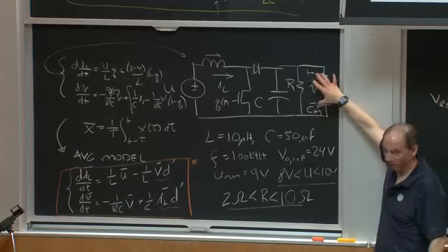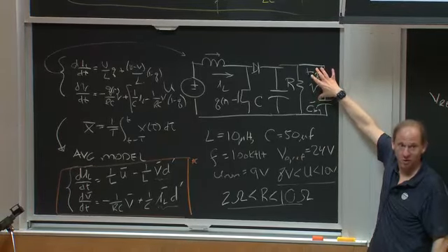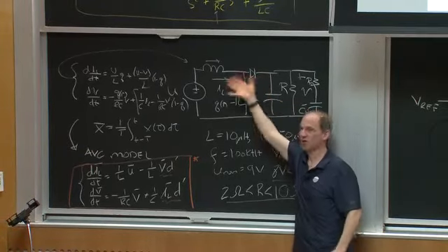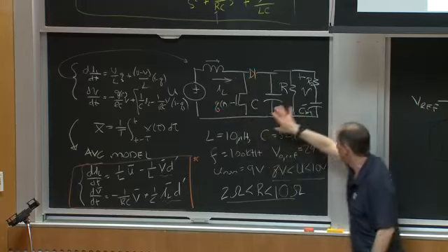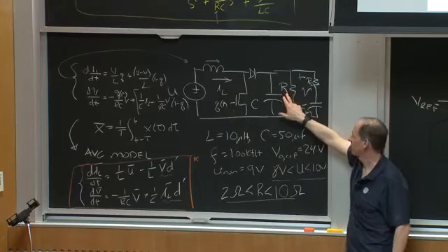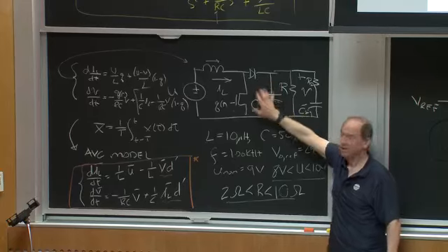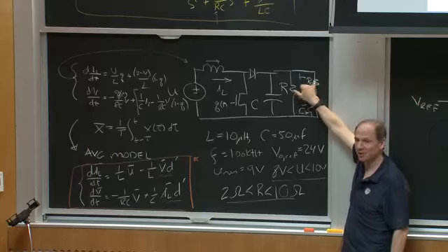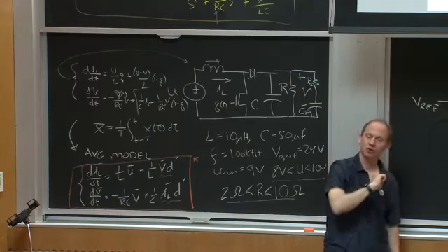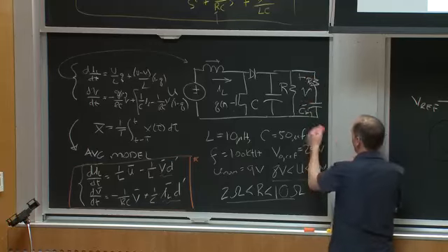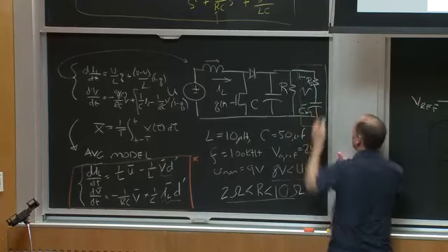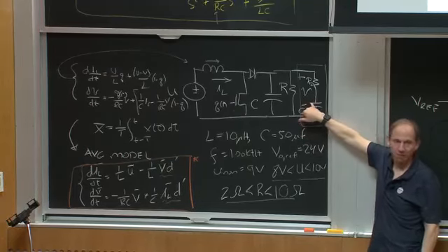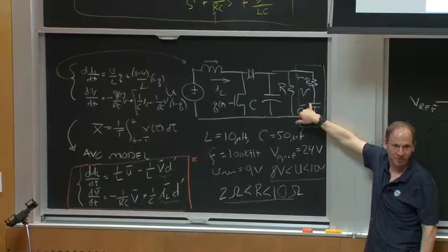When we talk about filter design, you'll also see these kind of damping legs, and you've seen it in snubbers too, right? The idea is, at frequencies near the oscillation point with L and C, if C looks like a short circuit, then RD is sort of in parallel with R and damps this. And then if R gets big or small, it always has RD in parallel with it. So if this was 2 ohms, and I was happy with the response I saw for 2 ohm damping, then maybe this damping leg added onto my converter would satisfy me, okay? And I also have some more big capacitance here to help me absorb larger voltage transients.